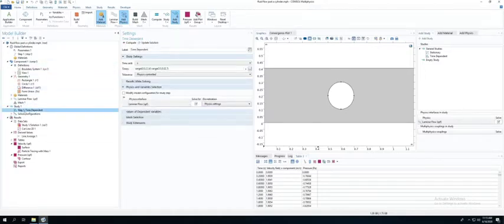If I come over here and look at my time dependencies, I can see that I'm doing this study from 0 seconds to 3.4 seconds at a step of 0.2, and then I change up at 3.5 to 7 seconds and change my steps to 0.02. So that means that at each one of these steps I'm going to have an average velocity.